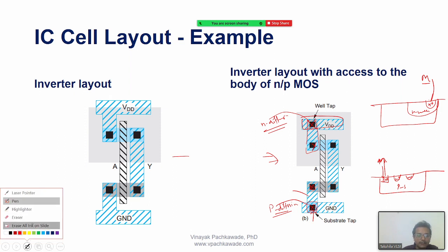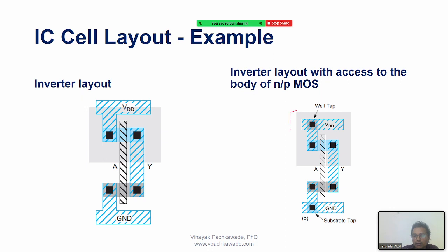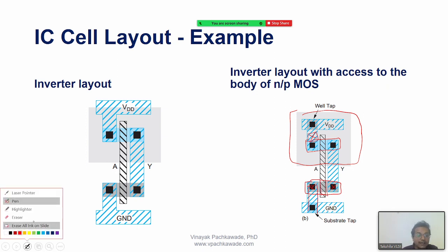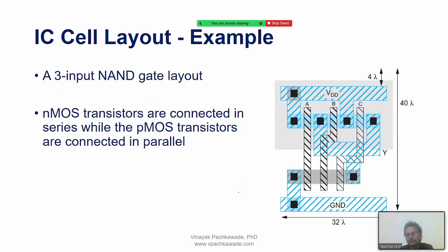So you see, when you use the transistors from the library to draw the layout of a particular circuit, you will already have these ready-made cells. What does that mean? You will have a transistor, and somewhere the body will also be connected to its N well. You will have this cell already with diffusions and the contacts established. You only need to draw the routing of poly and the metals. That would be the case when you draw the layout for a larger cell, a complex circuit.